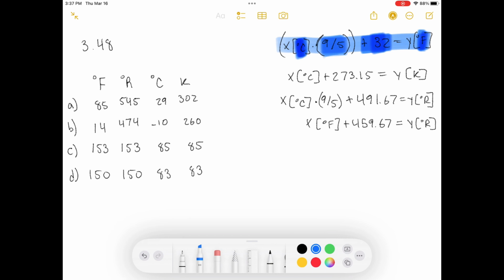So you have to translate that value, 32 degrees on the Fahrenheit scale, in order for the Fahrenheit scale to match up with Celsius. And that's the same thing with Rankine, because Rankine and Fahrenheit are, as you can see here, on the same scale, but they've been translated differently. So there's a translation value here that's different. Okay, so when you're doing temperature differences, the translation cancels out.